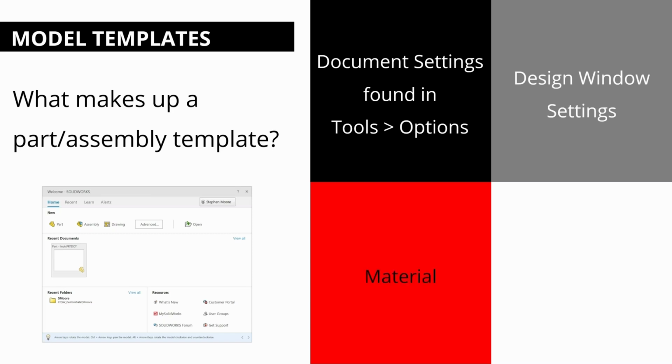The material itself, for efficiency's sake, if you only have two materials that you make things out of, steel, aluminum, whatever it is, go ahead and put that in a template. That makes it much, much more efficient. You don't even have to set the material. You make the choice at the beginning and you're done. So if it's a common material, maybe 80% of the time we use the same material, but then the other 20% we use other stuff, well, that's fine. Use that one template and then alter it for only the 20% time. At least you're saving yourself in the 80%.